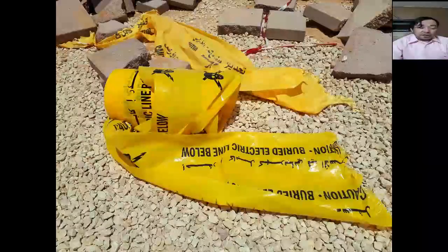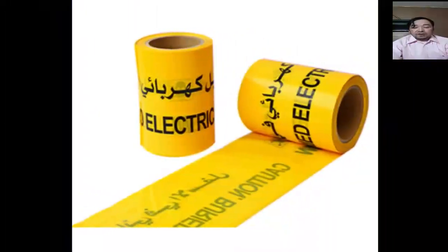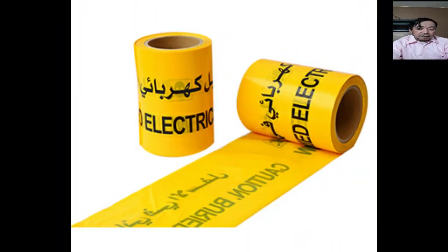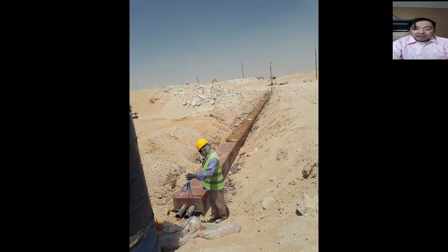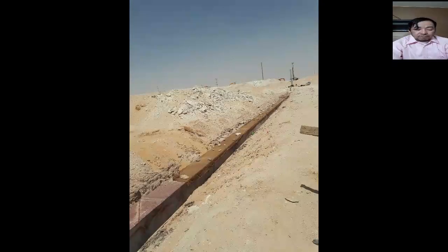In addition, a yellow warning tape shall be installed over the tiles or fence fabric. This method for power and control cable does not apply to grounding conductor. As I discussed in a previous topic, grounding is covered by another SAES, which is SAES-P-111.